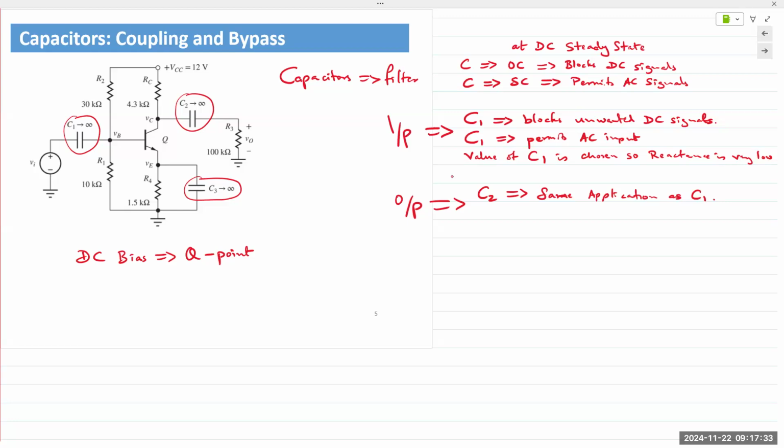Okay. So as an example, if we do not have a coupling capacitor at the output and we connect this output directly to a speaker, let's say an audio application, we'd have whatever music or movie we are playing available at the output. But at the same time, we'd have the effect of the DC signal coming out as a low frequency whine.